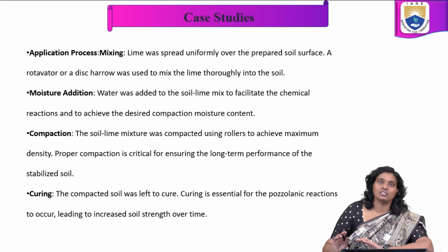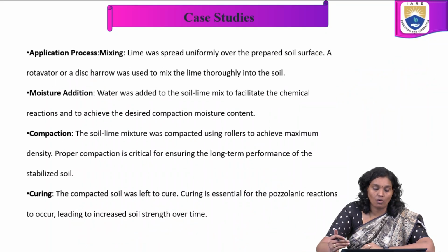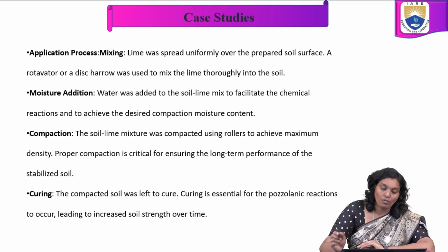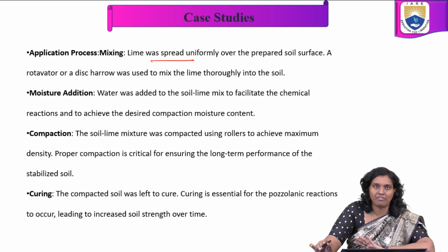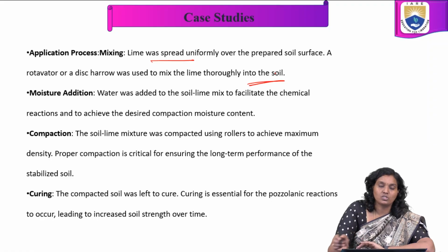Now the application process: mixing. Lime is spread uniformly over the prepared soil surface. A rotor or disc harrow is used to mix the lime thoroughly into the soil.